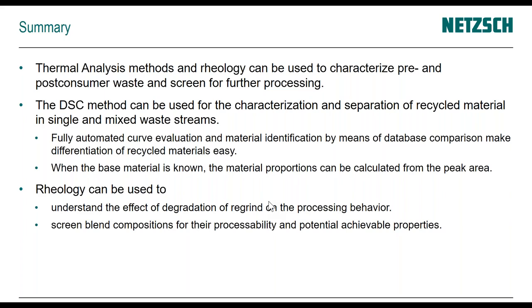is that you can calculate the material proportions from the peak area. And I also hope I could show you that rheology can be used to understand the effect of degradation when you reprocess a material and what that could mean for your processing behavior, for extruder, injection molding settings, and that it can be used to screen blend compositions for processability, for example, using compatibility to already get an idea about